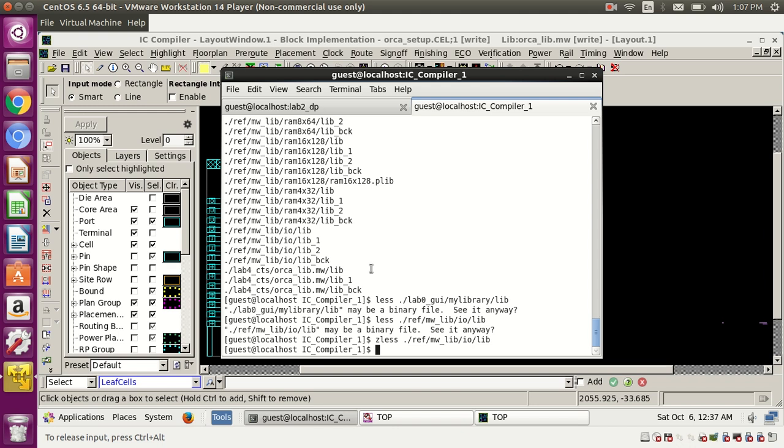If a flop has set multi-cycle path 10 by default, then only on the 10th clock cycle can it switch. No need to switch for all these 10, because the data will be stable. That's multi-cycle path. We have put set multi-cycle path 10, the data is stable, so we don't need it now. So based on our constraints, the tool figures out which data paths are going to be stable, and to which flops all these data paths go, and it will make